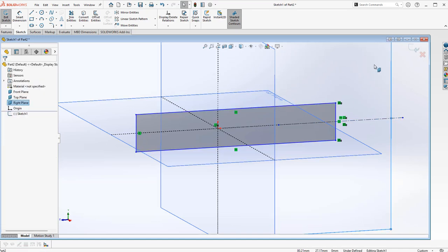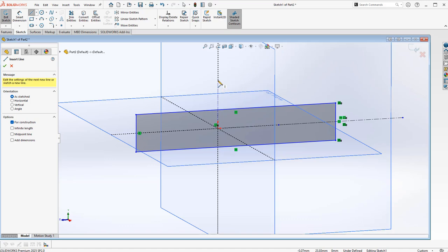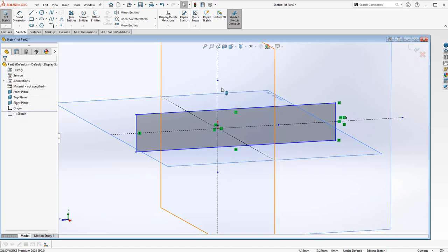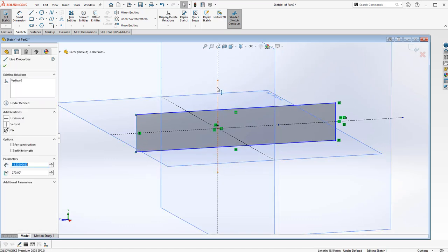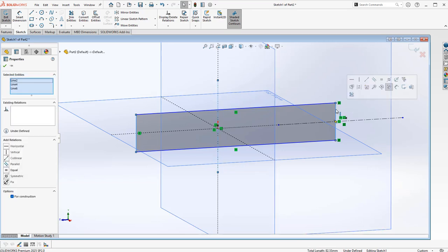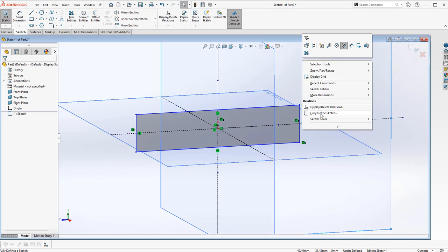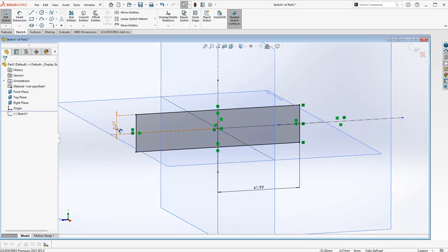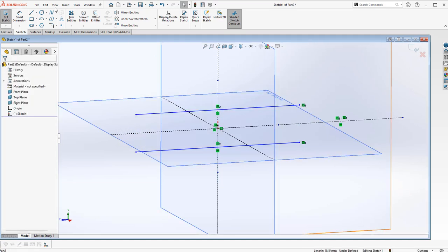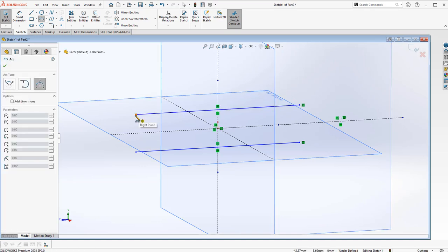And there. So you saw me move my mouse all the way around to the other side. Usually when I'm teaching a class, I focus heavily on the speed and effectiveness of the software. Look, I've got this symmetric tool and a pop-up window, which makes me a lot more efficient. If I hold down and fully define the sketch, it doesn't often dimension it the way I like it to. Also, I want to delete these edges and establish an arc at the end.